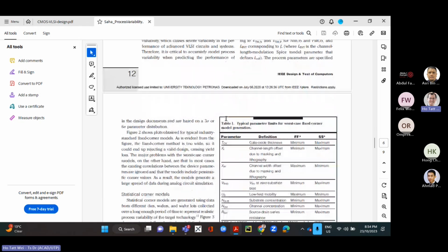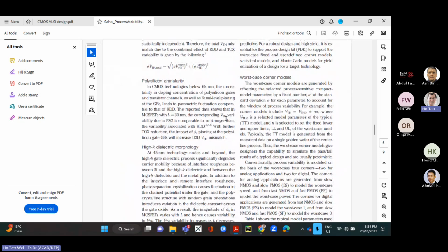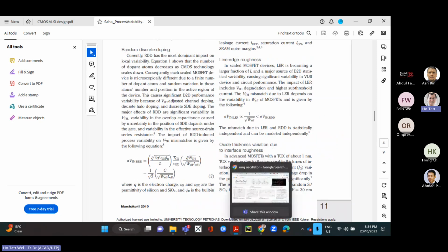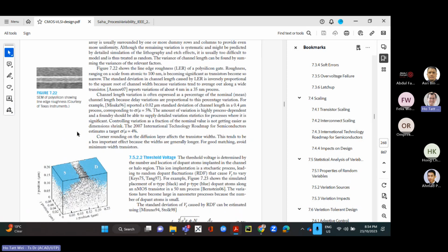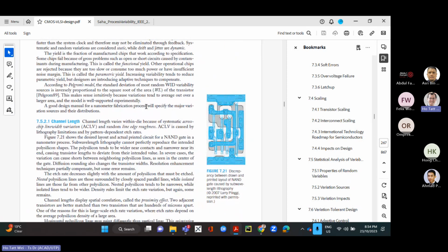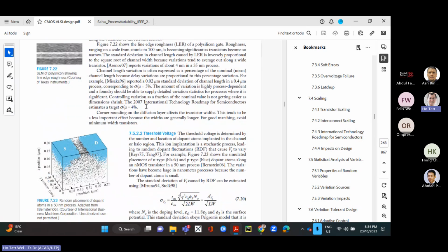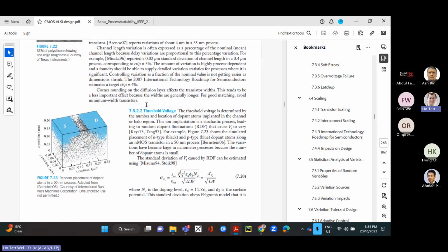This is where we start getting into the statistics, because you will actually be playing around with these numbers to estimate all of this. And the key point I want to disentangle for you, because there are many details and I don't want you to get confused: process variation has several physical effects that give rise to it. The West book covers three: oxide thickness, random dopant fluctuation, and line edge roughness. These three give rise to variations in threshold voltage. They contribute to a standard deviation in the threshold voltage within the same die.